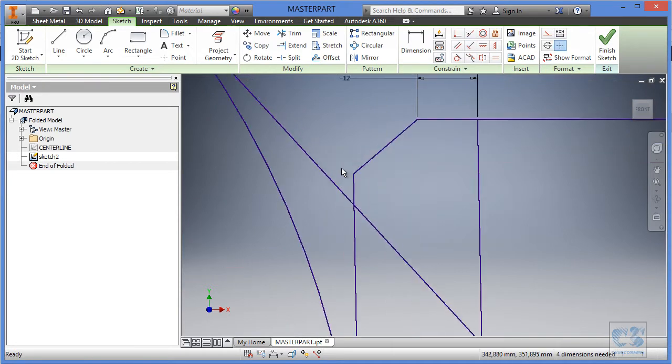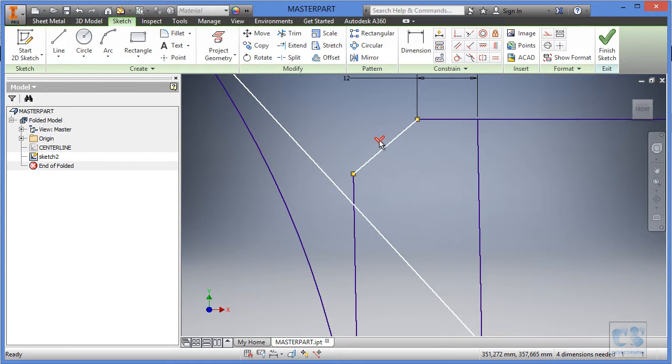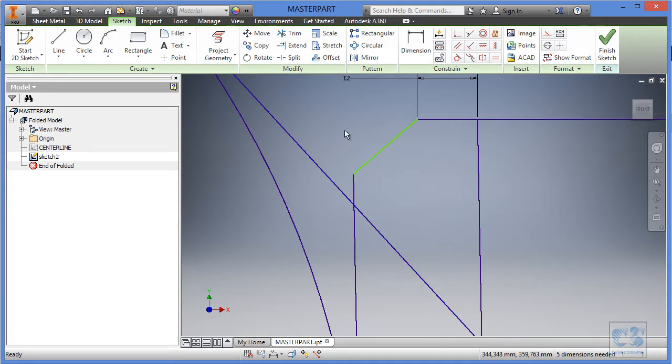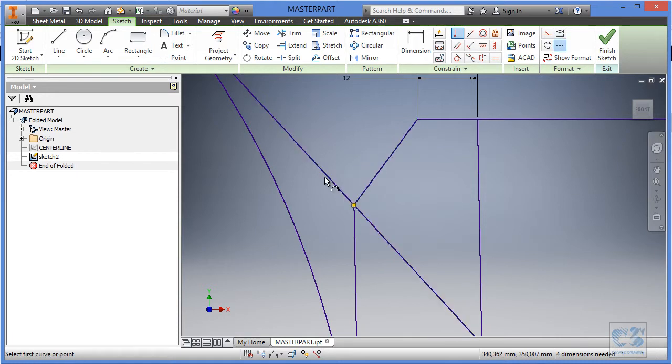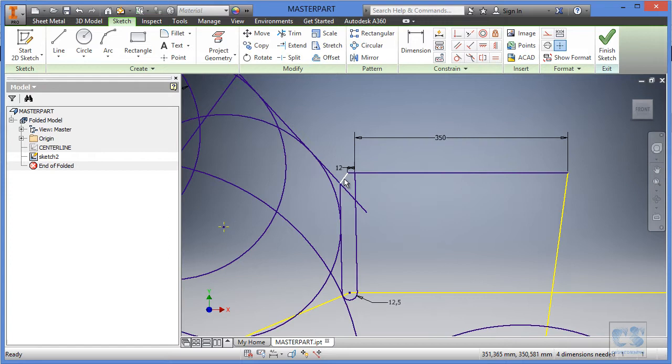And as you can see, the two are not touching. The perpendicular constraint is not a good idea, so I will remove it. And what I will do instead is just to add a coincidence constraint between the line. And now we have the deflector fully defined. We will not constrain this endpoint to this one, and you will see why later.